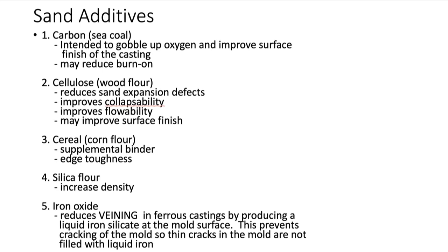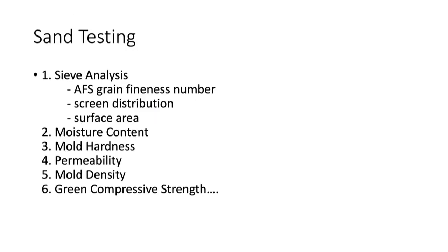Iron oxide can reduce veining. It's really just keeping the mold from cracking is what happens. Some people add iron oxide, usually to coarse sands.